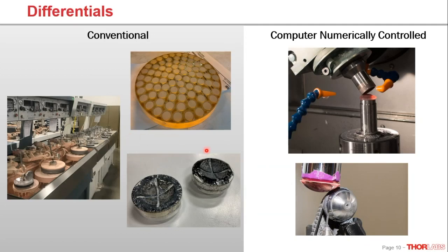In addition, it might not look like much, but here's an image of a couple of spherical pitch tools for producing some high quality spherical surfaces as well. This pitch allows us to have more of a conformal fit to the surface, which will produce a more even finish, minimizing any of the mid-spatial frequencies that might occur as a result of common techniques.